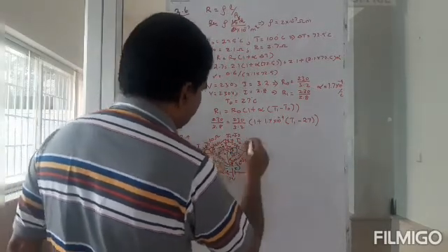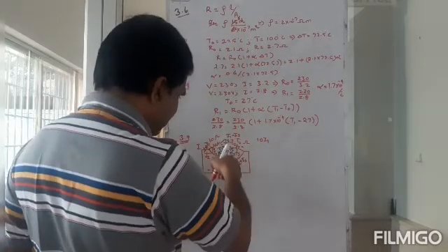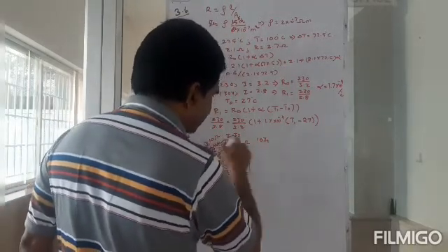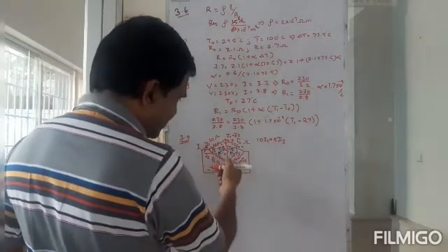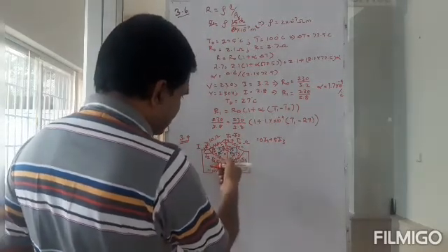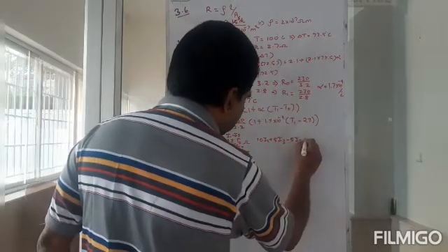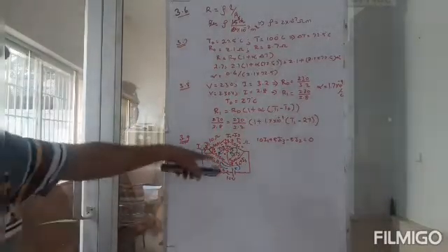I'm entering through plus. So 10 I1, and I come here, which is 5 I3, again plus, I'm entering through plus, and then I come here, entering through negative, right? So that's going to be minus 5 I2. Minus 5 I2 equals 0. That is my first equation for that loop.